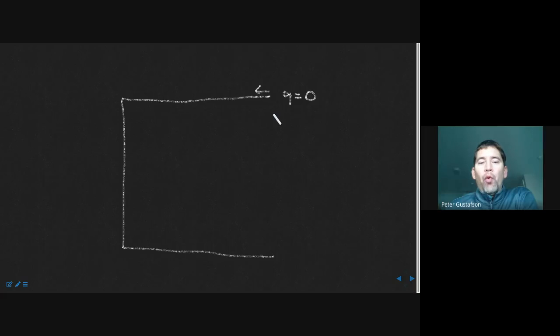Right now, we just said the shear flow is constant, so one might think that means it's going to be zero from here over to here, and then from here down to here, and from here down to here, and that doesn't make any sense, and I would agree with you completely. So what we need to recognize is that when we have this arrangement, we can still define our shear flow or our S coordinate system at that location, but we have this bending load carrying member that's present, this structural reinforcement.